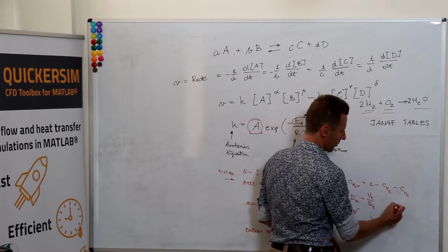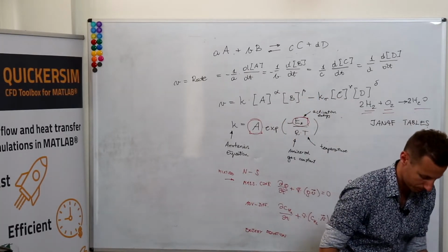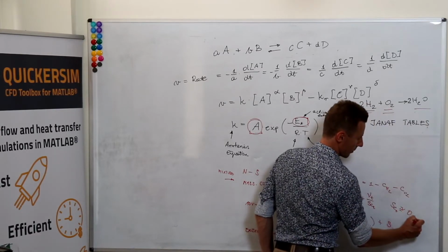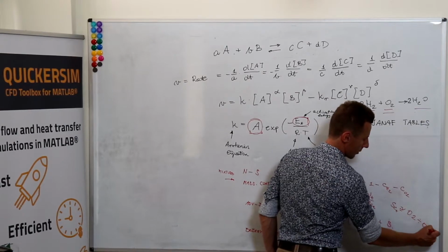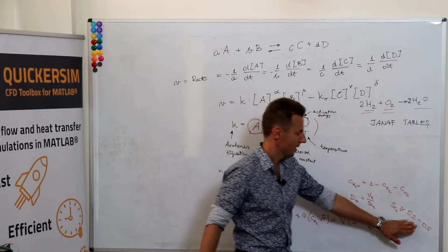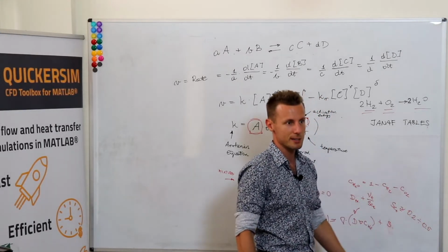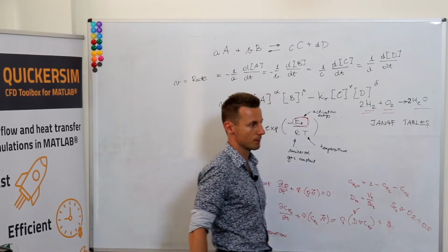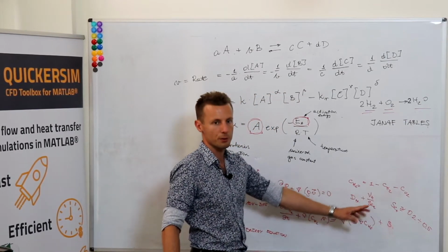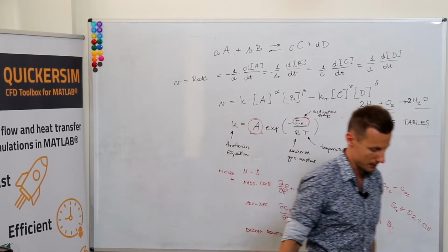And I think the turbulent Schmidt number ranges from 0.2 to 0.5, more or less. Typically a value somewhere in between is used for the whole computation. And this accounts for turbulent mixing of the mass of the species.